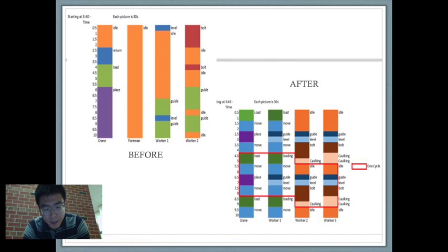Reading off the crew balance chart, we see that the foreman and man 1 are mostly idle in the process, so it would be better to let the foreman replace man 1 to reduce the amount of people on site. For the transporting stage, we need a worker to prepare the panels for lifting and a crane operator to move the panels into place. For the placing stage, we only need 2 workers to guide, level, bolt, and caulk the creases.